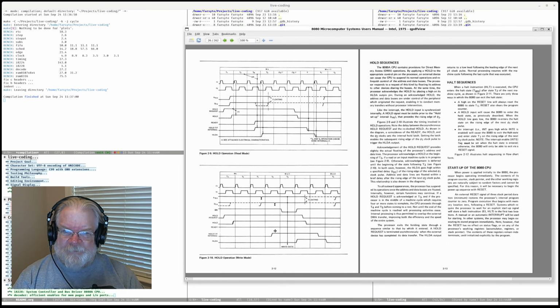And T3, so we need to set up a generic M2 for fetching byte 2, because we're going to do this a lot. So second byte of, we're going to need an M2 for second byte of address, and that will need to turn over control to the instruction during M2T3. So M2T1 and M2T3 we need to have in the processor so somebody can set those up.